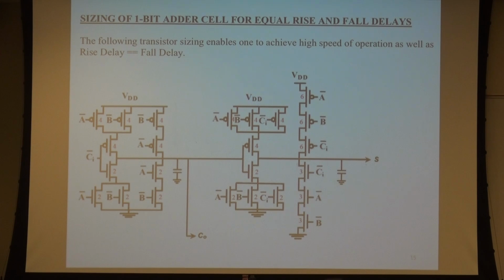Ah, okay, good. So, how do you now size them? We have recognized that using the 24 transistor configuration, we can design the carry, the 1-bit adder, and this is the carry out bar without the inverter, and this is the sum bar. We have seen that this is the expression for that. So how do I size them?